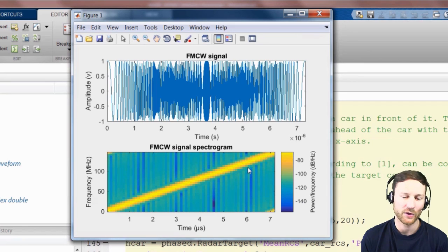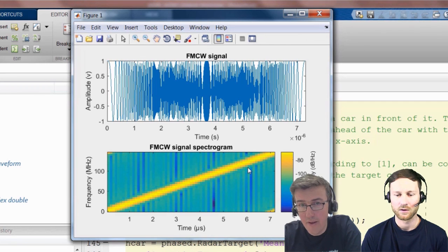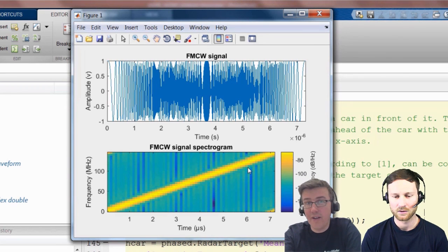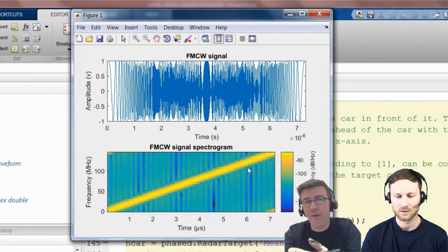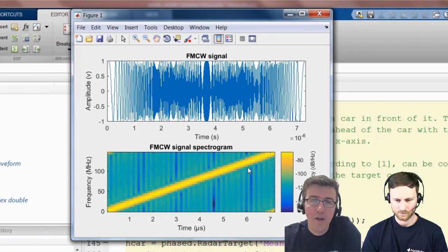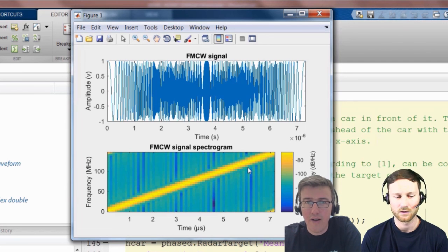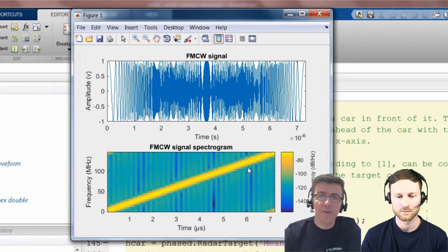When you see that frequency plot over time, what does it tell you? Is there a distance getting bigger, getting smaller, or what do you see when I have a look at this diagram? So this is just the signal that you will send, and you will receive back another signal which will be different than this first signal that you have sent, and you measure the difference in the frequency, the beat frequency, to analyze the range, so the distance of the target, and also the speed of the target.